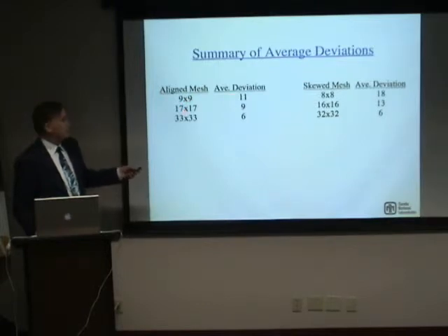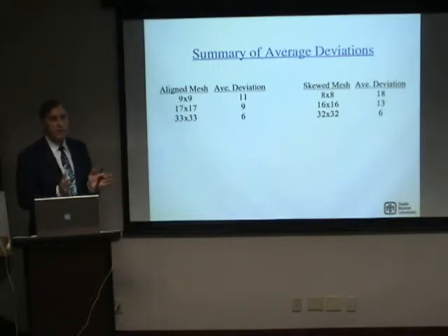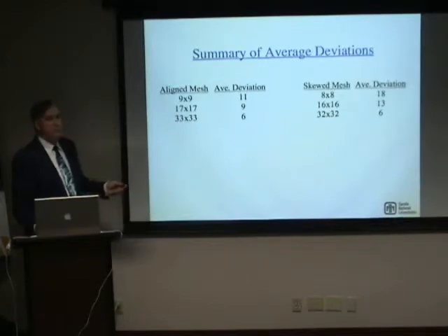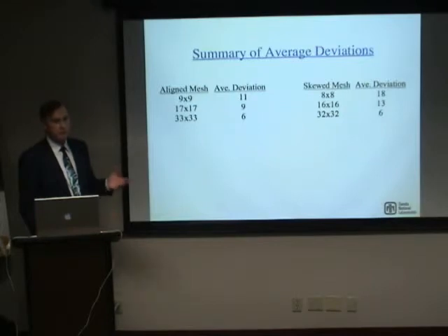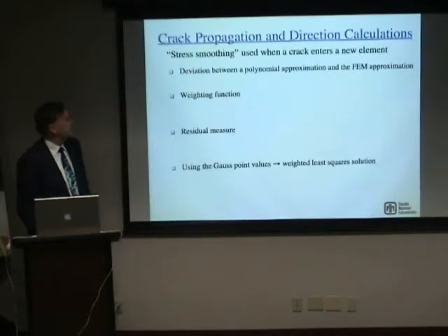And this ties back to the thing that I mentioned earlier in terms of what you're enriching. You have two things working against each other here. You'd normally think that with the mesh refinement you'll start seeing considerable improvement, but the problem here is that in this case you're refining the mesh, so you're getting more polynomials, but if you're doing it only based upon intersect, you're getting a smaller and smaller region over which you're applying the enrichment. So that's not helping you, whereas the mesh refinement is.